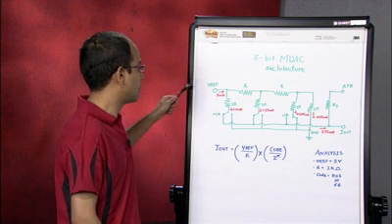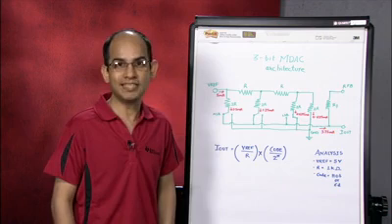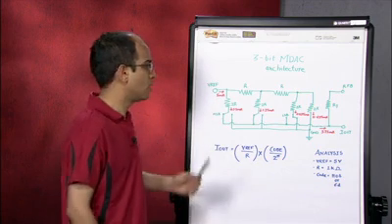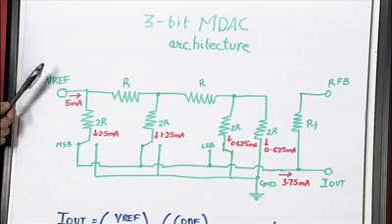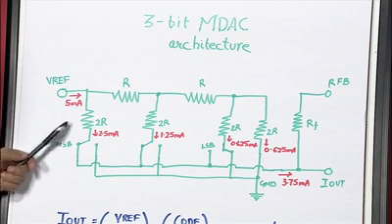That means the reference circuitry for the Vref pin is very easy because the resistance looking into this Vref pin never changes. Now, going back to how much current flows into this Vref pin, it would be 5 volts divided by R, which we calculated, which is 1K. The current turns out to be 5 milliamps.